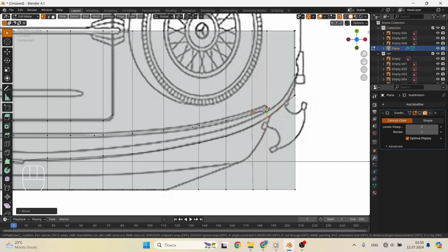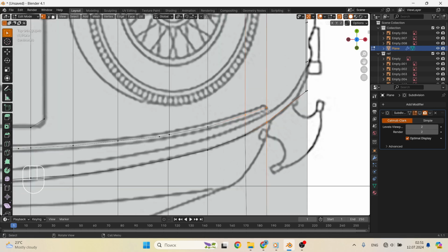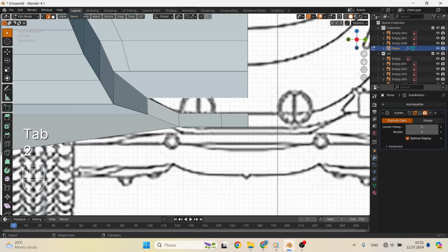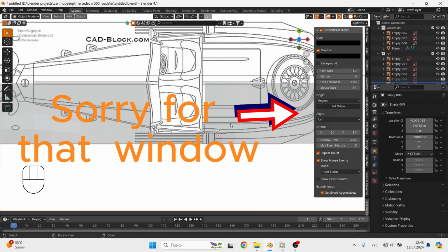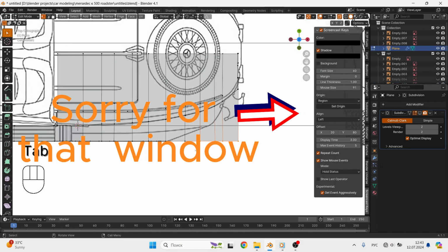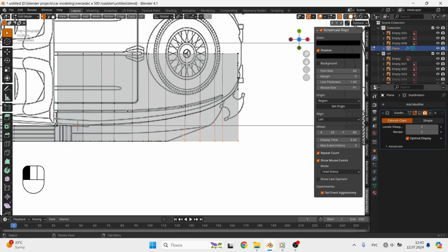They can be added to the active object using the Add Modifier operator, the Add Modifier button at the top of the Modifiers tab in the Properties, or using Shift-A in the same tab. New modifiers are always added at the bottom of the stack. There are many built-in modifiers, but Blender also allows users to make their own modifiers through geometry nodes.